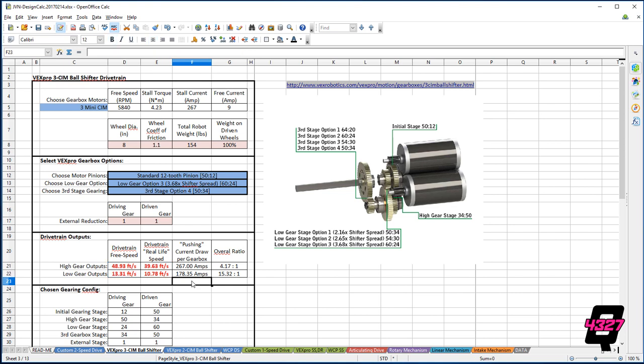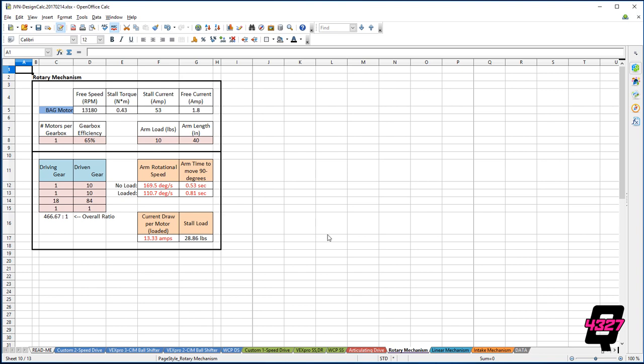Next, let's try making decisions on a manipulator using the spreadsheet. So let's suppose we have an arm we want to move through different angled positions. In FRC, we want to move between positions as quickly as possible to get a game piece and then score that game piece. Our limits on this are the amount of amps of current drawn to do so and the mechanical strain of the chain or gear or whatever is used to move the mechanism. So let's suppose we've got a 12-inch long arm with a 3-pound weight on the end. So you're going to input that data in the spreadsheet as I'm doing here.